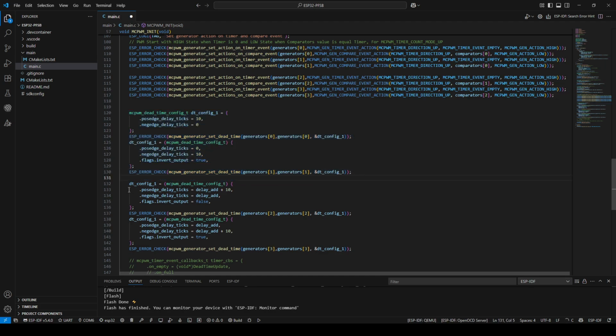And then this is for the lagging leg, for Q3 and Q4. In here, for this signal to work, you need to add some dead time. If you put 0 in here like this, it will not work. I don't know, it means the compiler will see that we don't change anything to this signal, so it will skip this even though we put true, and the signal will not be inverted.